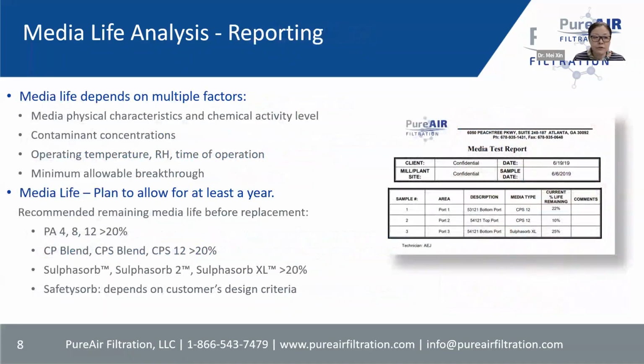So after the lab finishes all the tests, we are going to file a report. The media test report summarizes the comprehensive chemical analysis that predicts remaining media life. Also, please remember, media life depends on multiple factors, including the physical characteristics and chemical activity level, and also depends on your site: the contamination levels, the operating temperature, relative humidity, and time of operation.